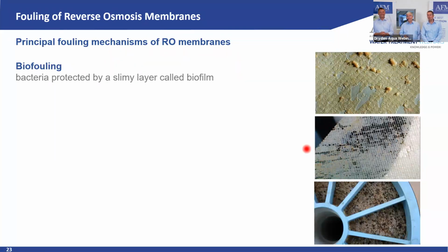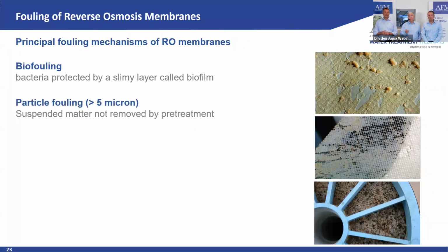Yeah, exactly. And then maybe the worst thing is if you can see something like this here, then you really get into big trouble with your membrane. That's the mesh spacer. Yes, really. If this is blocking, then you have a problem. With AFM, we can make sure that this will not happen here, because this mainly happens because media filtration generates too much fouling, and then you have this kind of problem.